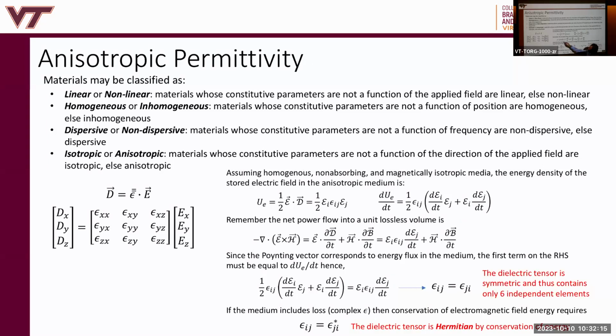So here we're talking about the divergence of the power. Power, E cross H, is a vector field, and it describes a flow of power. So the direction is the direction of the power flow. The magnitude is how much power density. So I have a cubical volume. If I have, so this is some volume, right? If I calculate the divergence of the power flow, I'm adding up the flux of power penetrating the surface that's surrounding that point, right? Or that volume. Let's say that I have more flux lines coming out than going in for that particular volume. What does that mean? That what's inside of that volume?